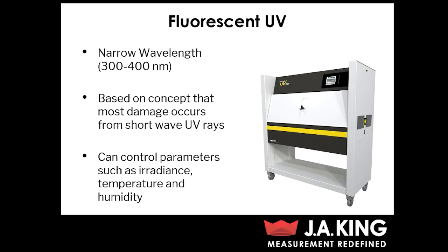But also fluorescent UV testing is controllable. So you can control parameters like your irradiance, which is really just your light intensity, and then your temperature and humidity as well.